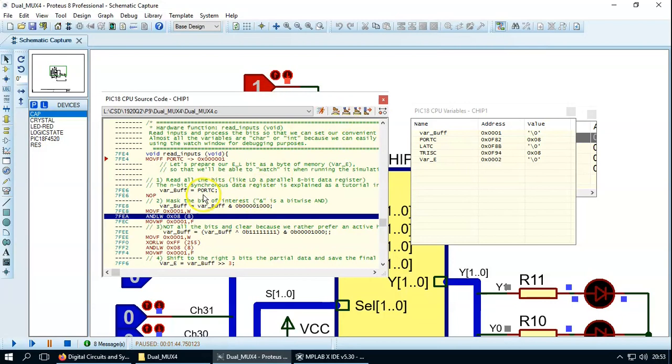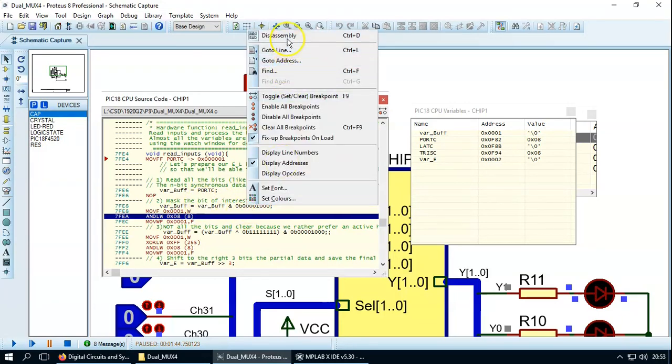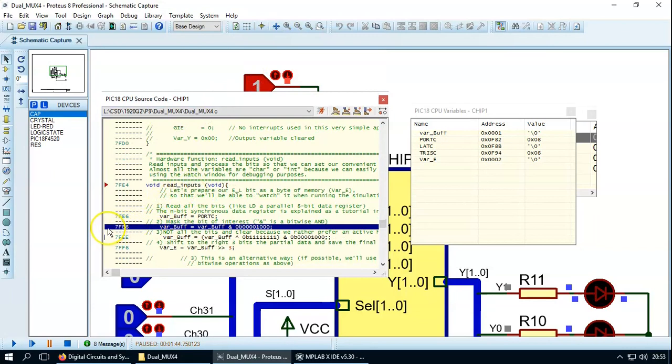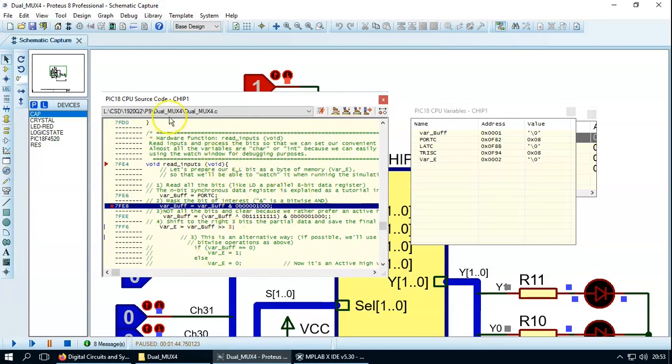It's shorter, naturally. So if you have a given instruction in C, you can click now on the left, and this red circle is what is called a breakpoint. This is going to allow the program flow to be stopped here. The code is going to be broken and you will stop the execution of the code here. And what is the meaning of this? Well, because you are in an infinite loop, you can run, and when you run continuously, the machine is advancing in time. Look at the indications down there, the time is advancing.